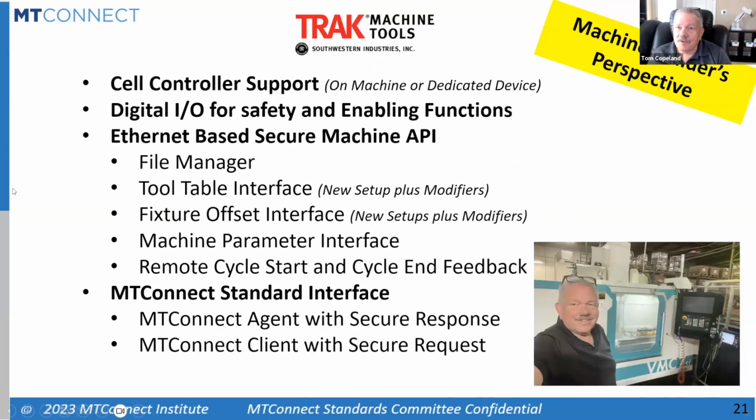And for me, I'm kind of on the cell controller bandwagon, where there is a centralized piece of software that orchestrates these machines. And also, since I am an OEM, I'd have to deal with safety. So digital I/O is not going to go away entirely in my mind. You're still going to have e-stops and enabling functions scattered throughout your cell to support the safety rules that still exist today.